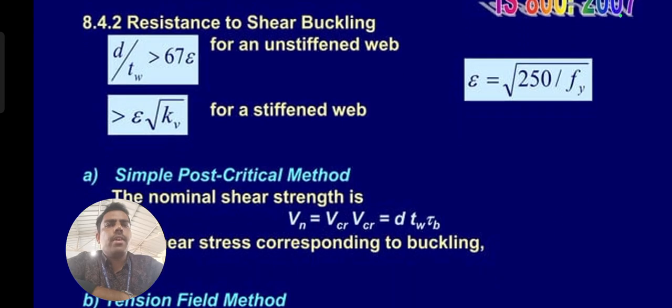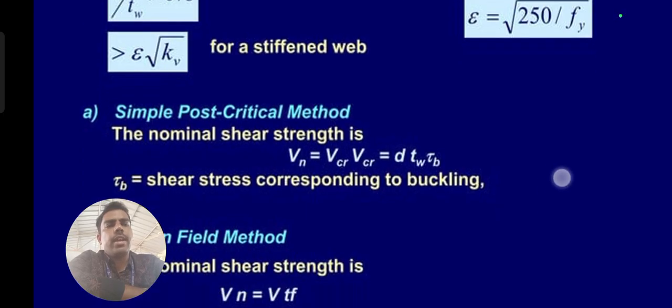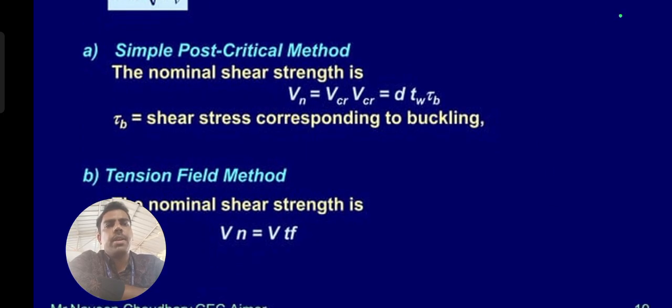And here we have to find out the section classification, that is, whether the section comes under plastic, compact or semi-compact. For this, we already learned in the previous chapter how to check the cross-section classification of that particular beam. So we are using IS 800:2007. Based on that IS standard, we have to find out the classification of that particular section.